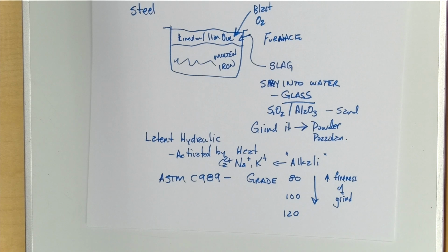But it has a really interesting behavior. Slag, when it's mixed with Portland cement and it's cured where there's not a lot of oxygen, like under a curing blanket. Remember we covered our samples with blankets? Under a curing blanket or under water, it turns green-blue from the sulfides, the sulfur compounds that are present.